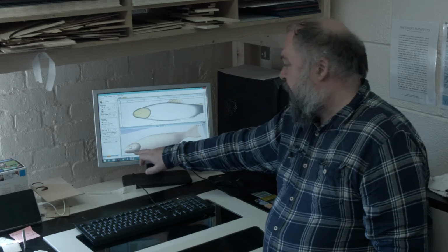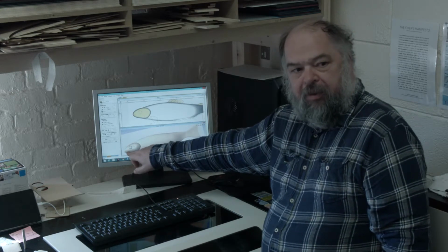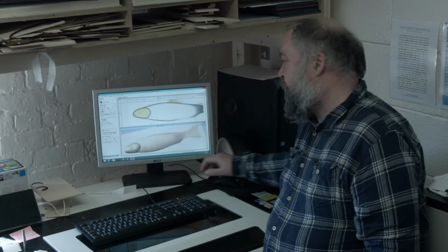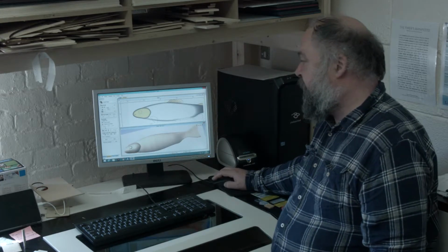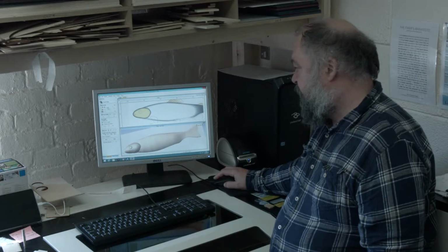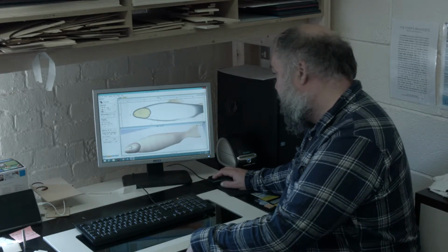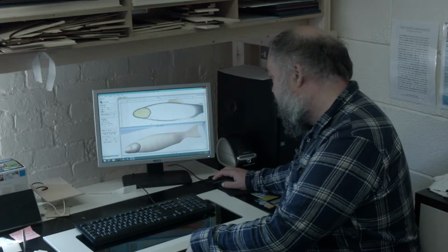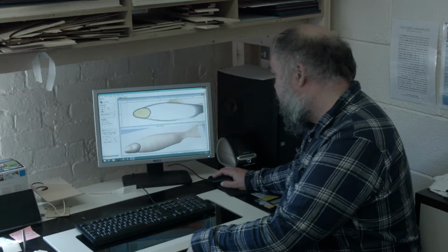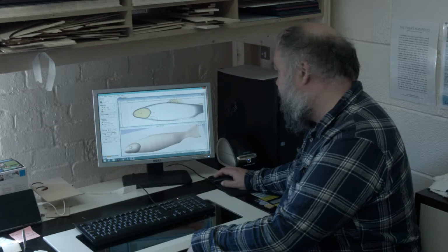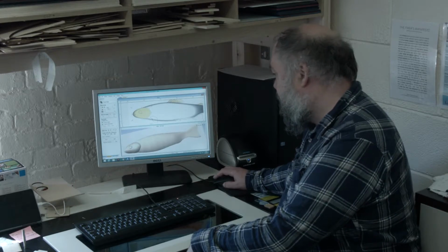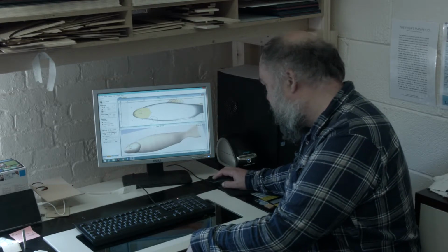What I want basically is I don't want it to be up at the front edge, I want it to just be up at the back edge, so I can actually put a tilt onto it. So using the tilt, set from there to there, and it sets it initially at 10 degrees. We can alter that.